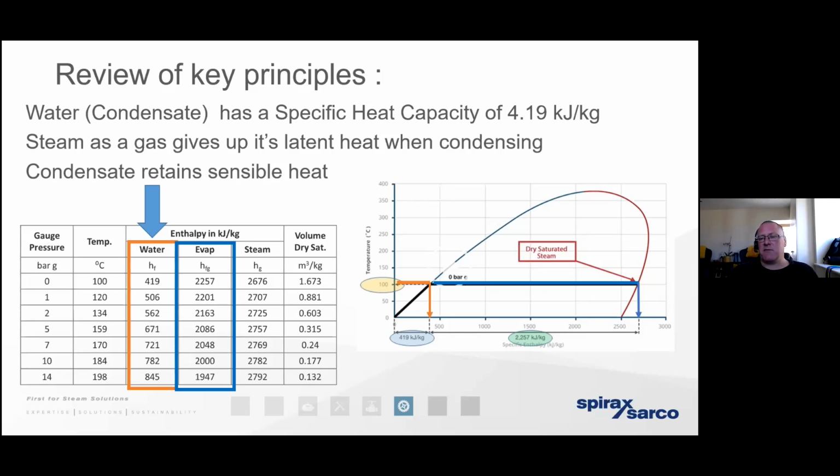So let's say, for example, we weren't on top of producing steam optimally in the boiler house, or it could well be that we got a contaminated source of fuel. If we fail to put the full latent heat, that's demonstrated on the blue line here, into that boiling water, then the water would be unable to fully evaporate and produce a mass of steam that we'd refer to as dry saturated. That's critically important when it comes to understanding the steam condition, dry saturated steam.